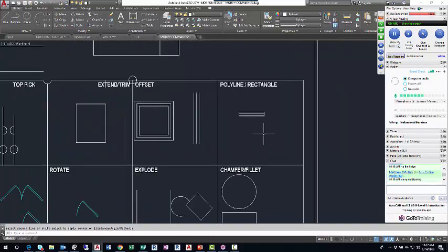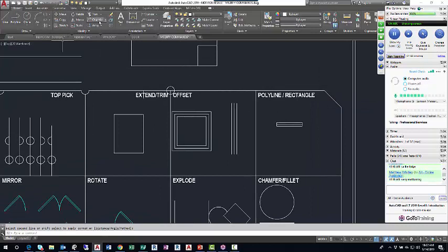I'll do another one. I'll do one up top. So it does retain that chamfer distance. Once you've plugged in a chamfer distance, that chamfer distance stays in the command until you change it. So I can chamfer things, lines or polylines really is the max. Now I've probably chamfered this particular line to a point where I can't chamfer anymore. The distance is too large. Chamfer. There's that one. That one worked, but I didn't leave enough vertical or horizontal line there to repeat that.